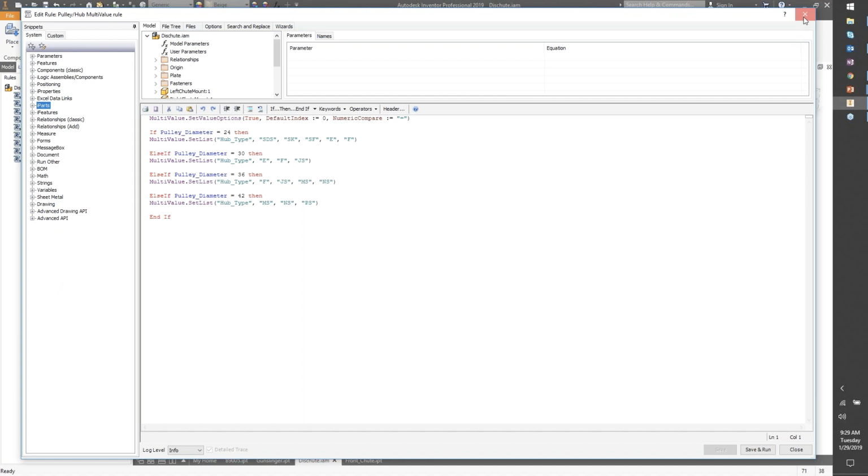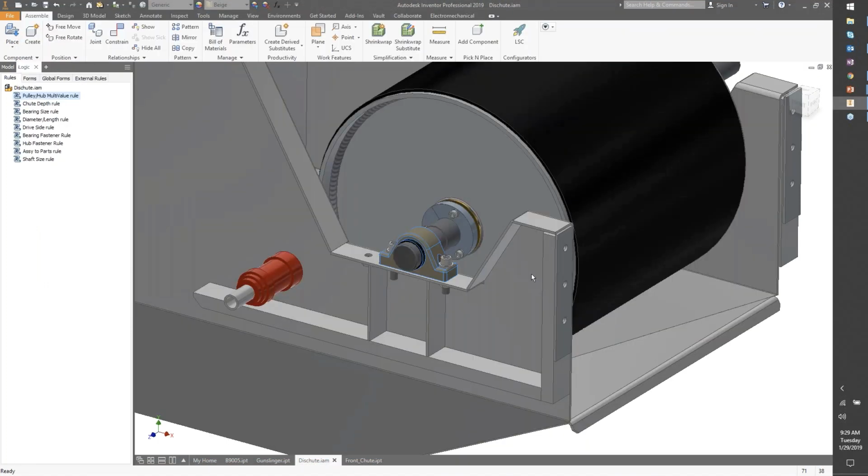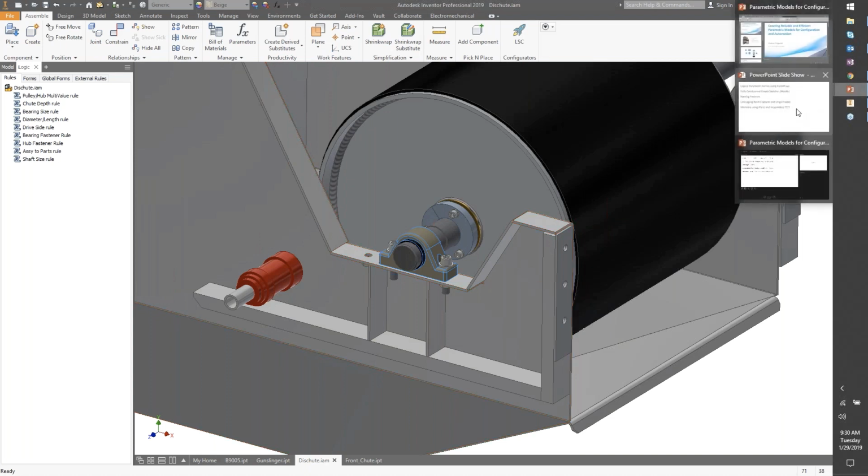simply because if we're already going down the path of creating logic and developing configurations based upon condition, iParts really are the same thing. You know, we can change the configuration of an iPart by assigning a condition and changing the row of that iPart. So we can do the same thing by leveraging my workflow that I have shown here previously.